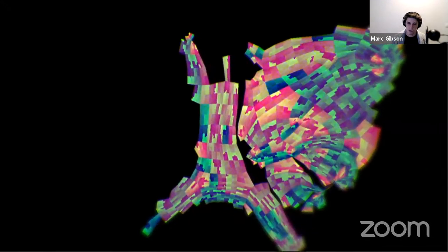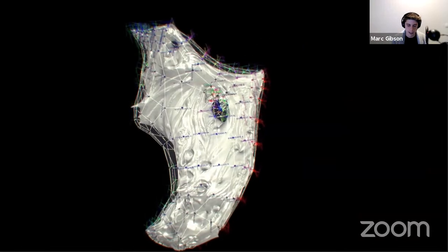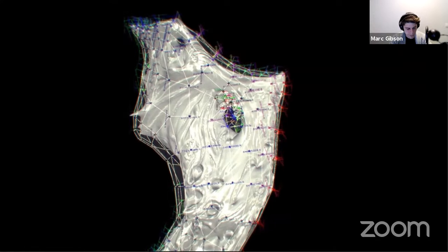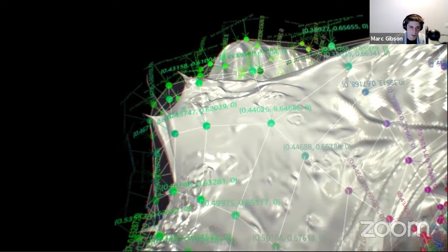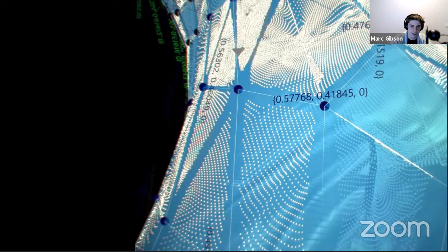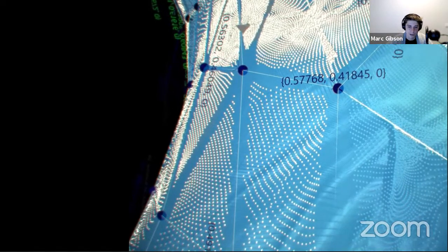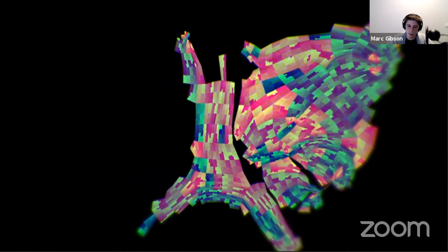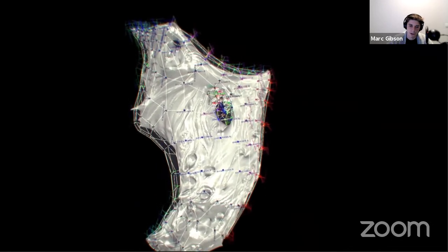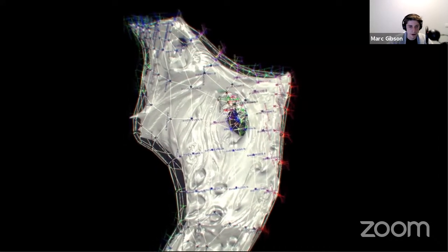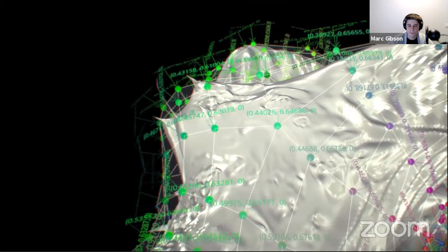So I looked at a different technique to try and essentially map on a more designed unwrapping procedure. And so the challenge of this is the geometry is quite high resolution and topologically complex, which makes it very difficult to unroll in large pieces. You could obviously unroll it in lots of little strips. So to do this, at the initial stage, so before the geometry grows, I made a low resolution offset of the object and unrolled it flat.